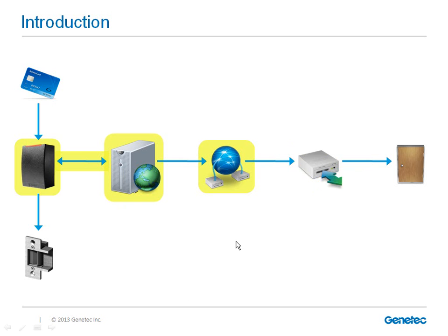The second issue is where the units are dropping offline. This is commonly something on the unit or the connection to the server, but could possibly be a problem related to the access manager as well. Now, when the door is not unlocking when it should be, we'll need to take a look at the lock itself and the wiring, and the unit to make sure the output is configured properly, as well as take a look at the schedule that we have set up on the system.